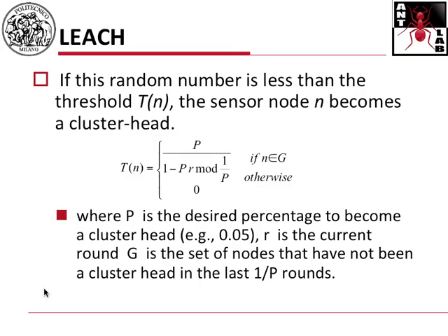What do you mean by power? I mean, maybe it's better that each sensor considers its remaining power. Exactly. So basically, this selection rule disregards completely the battery storage, so the current level of the batteries each node has. Or in other words, it assumes that the network starts in such a way that all the nodes share the same battery level. Okay? If all the nodes have the same battery storage or battery capabilities, this is fine in prolonging network lifetime.